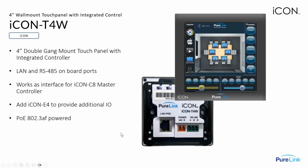All right, so the first one up is the 4-inch wall mount. This has onboard LAN. The touch panel is powered PoE. So as soon as you connect this touch panel to the network switch, as long as it supports 802.3 AF power, this panel is going to boot up. And you can program this panel directly from the Easy Control software and just be up and running in no time with your control system.